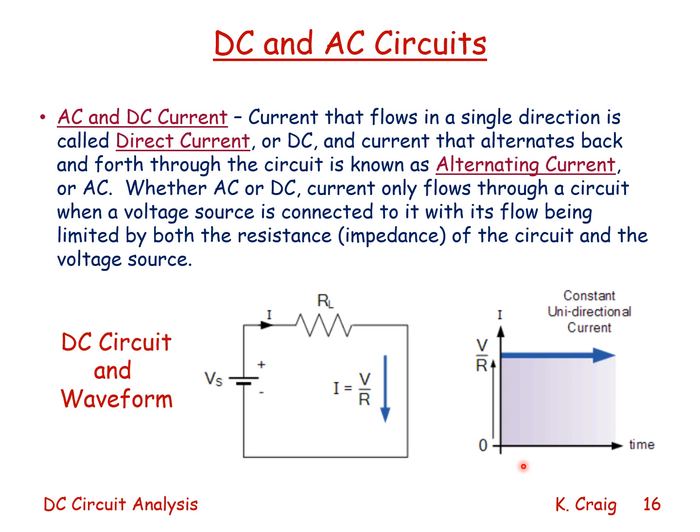But in the real world, a resistor always has some parasitic capacitance or inductance, and so the response for the current as a function of time, once the voltage is applied to the resistor, is not instantaneous, but very fast. Keep this in mind as we deal with real components versus pure and ideal components.